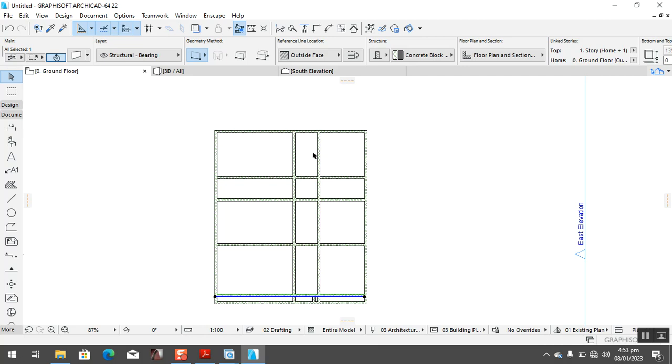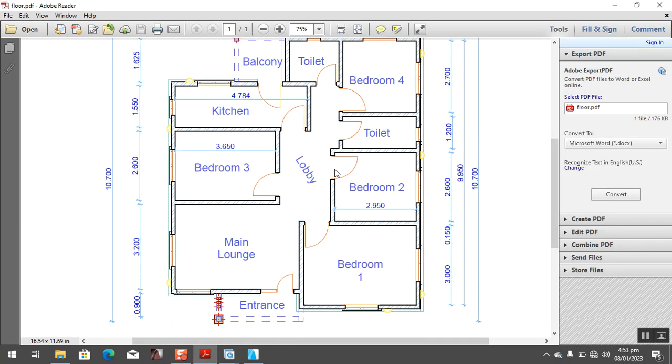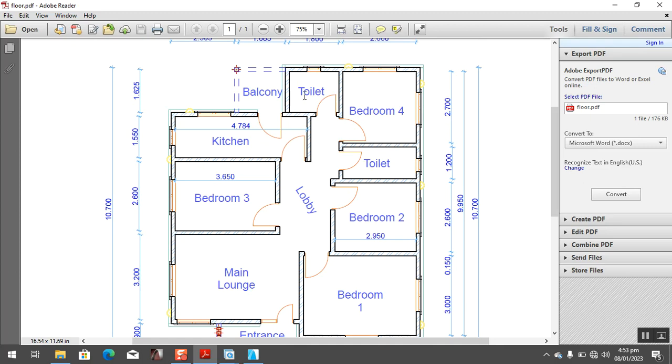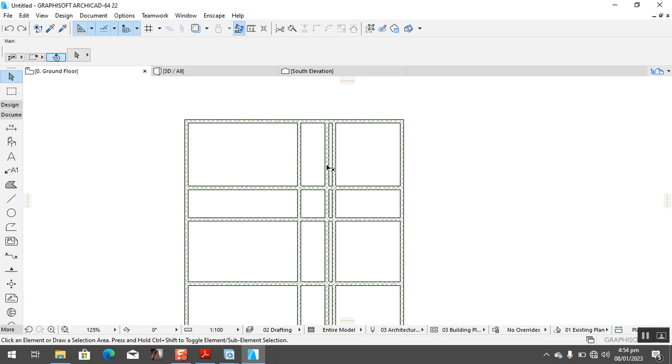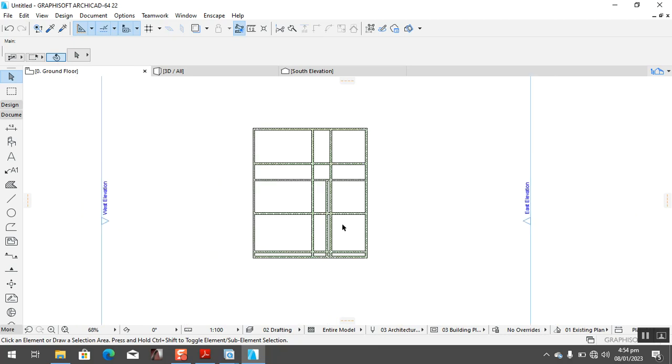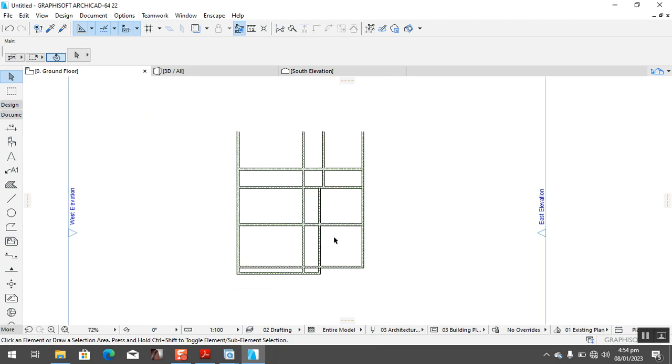So we're going to delete this, I guess. Let's bring this back. Let's check what we're deleting now. This wall is running straight. This particular wall is going to run straight to this bedroom 2 walls. So we're going to delete some walls here. We'll come down to this place. We'll delete this. You put your hand on control, the sign will show you. Right click, that's delete. Okay, then here we're going to delete this. Then we're going to delete this and this and this, because it's no longer necessary.